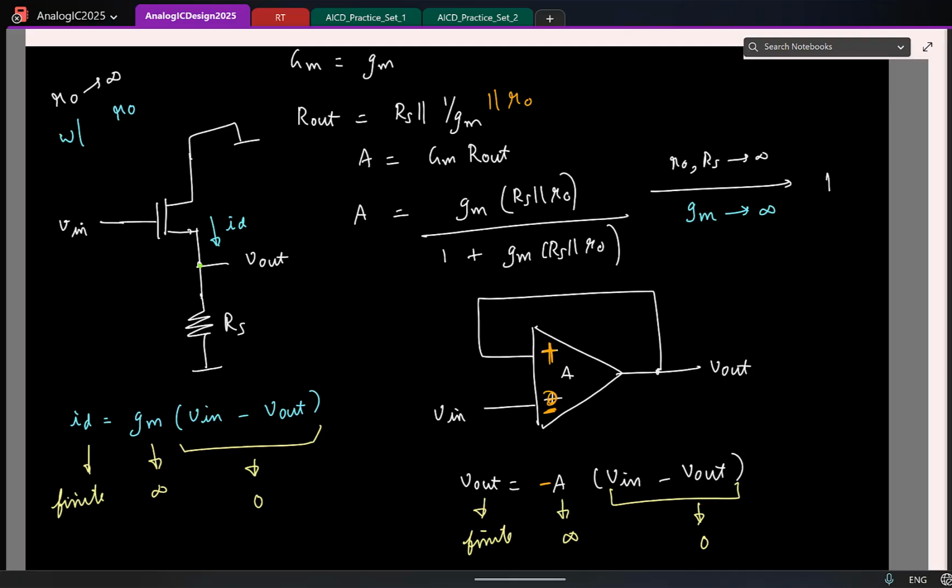Okay. Now remember, in practice, when I have this, the op amp is in positive feedback. And the moment you have positive feedback, output sort of blows up, and in practice it saturates. Correct? So if the output has saturated, do you think this relation is valid anymore? The relation is not even valid. So which means you can't make this argument. So what should be satisfied for you to make this argument? You should have negative feedback.